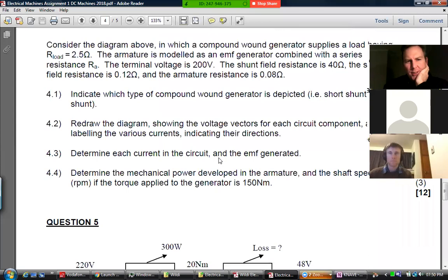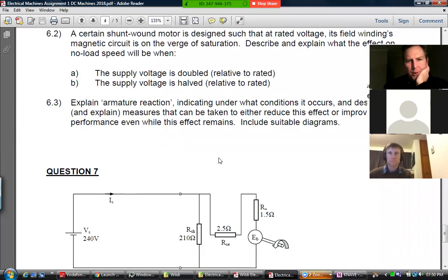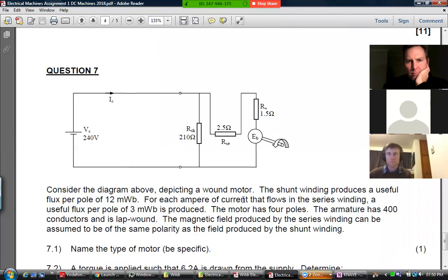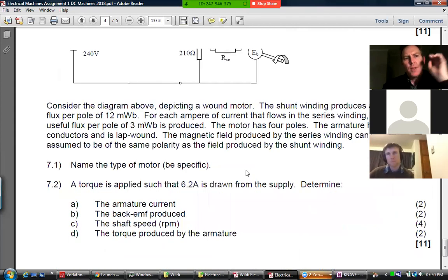So this one had some different questions, but some of the same. Okay, yeah. I think it was maybe trying to work out the back EMF. Maybe, yeah. So your E equals your V minus your armature voltage minus, right, your voltage drop of that resistor as well.